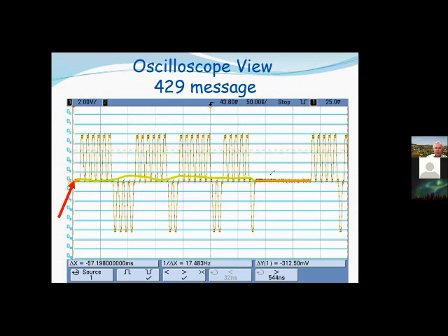Some of the things that you check for if you're on a scope: this gap over here has to be a minimum of 4 bit times. There should be exactly 32 bits. And if you measure the time, you see here, this is 50 microseconds per box.